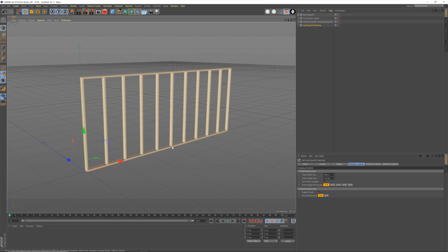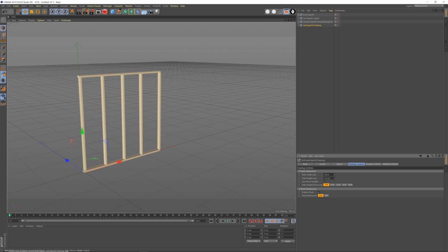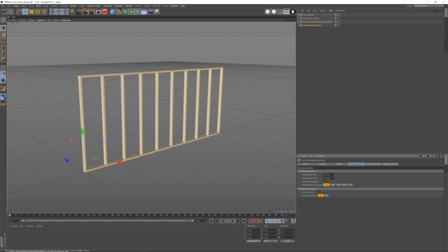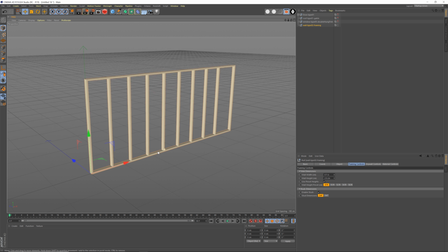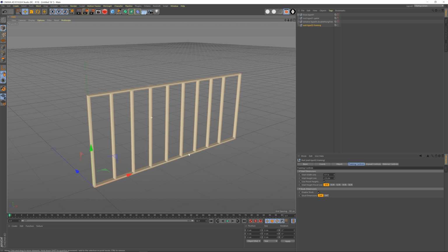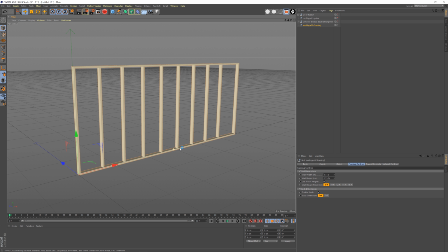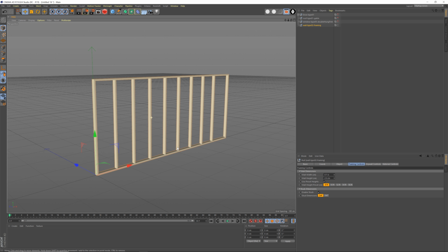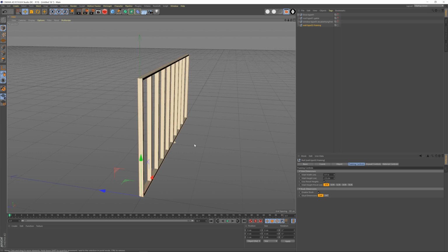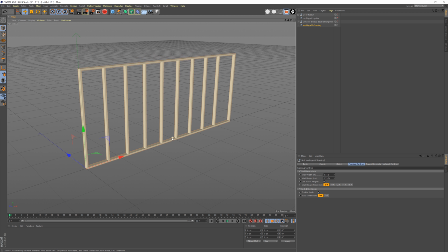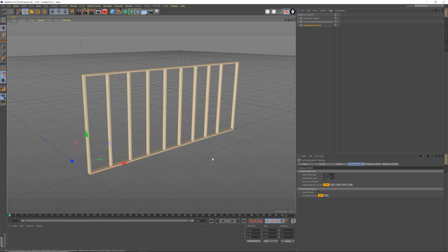We have the width, and so as you drag this and make it less wide, you'll see that these beams or studs get added, and this is the framing aspect of this object. And they're 2x4 studs, and they're being added every 24 inches. There are other standards for building house walls, but this is the one that I decided to go with. And again, these aren't structurally sound. Like when I finish building this house, you're not going to be able to take it to an architect and say, build this exact thing. But it does give us somewhat of a real world based structure when we're building houses so that we don't just build really weird dimensioned rooms that don't make any sense.